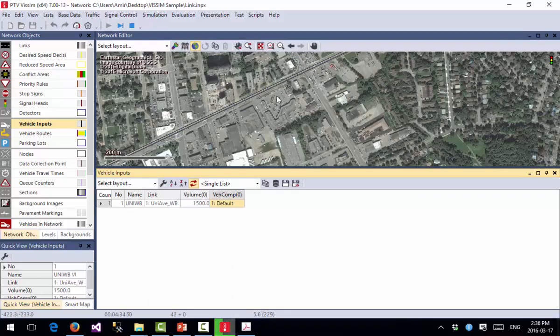So here is a very simple example of how you can simulate a very simple link, just putting some values there. And for example, I think you have already covered the link flow relationship, for example the Greenshields or Van Aerde model. So you can simply model this link here, and then you can extract the volume, the density and other information, and you can draw the charts that you want to draw in fields or other network types. So now let's go to a more sophisticated problem.